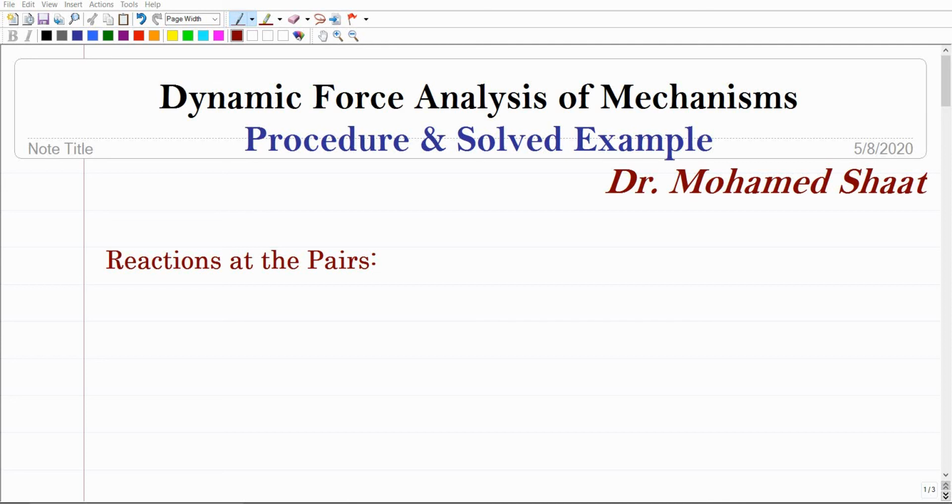Also, we discussed the case where you have a two force and couple member, like two forces at the ends and one couple in the middle. We said that for this case the two forces at the ends will be parallel and of the same magnitude but of opposite directions, and there should be a normal distance between them. This normal distance depends on the torque that is acting on the member. So this is, very quickly, what we already discussed before. Again, the objective is to show you the general procedure, in addition to giving an example on the things that we already covered so far.